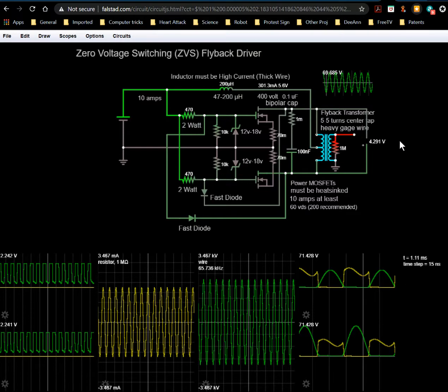If you try to wind it clockwise for half of it and then counterclockwise for the other half of it, the fields will actually cancel. So you won't actually form a magnet. It'll just be a wire with the fields canceling each other, which is an interesting effect, and it has its uses. You can actually control fields inside a magnet by using another totally separate coil controlled by a totally separate circuit, because they are connected magnetically but not electrically. So you can do a lot of interesting things with transformers if you have a bunch of different taps on them, like you typically see in a PC power supply transformer. It's a whole little area there.